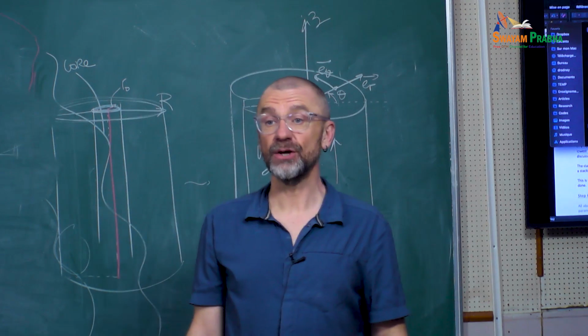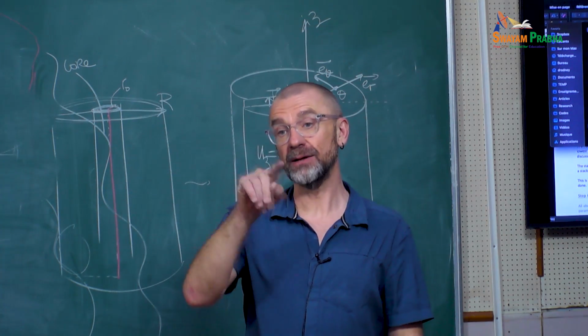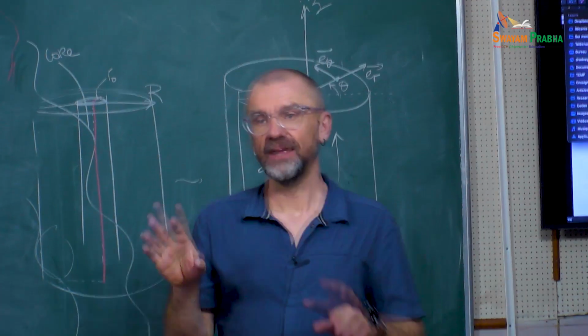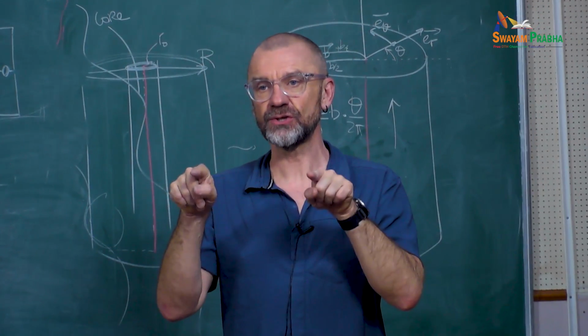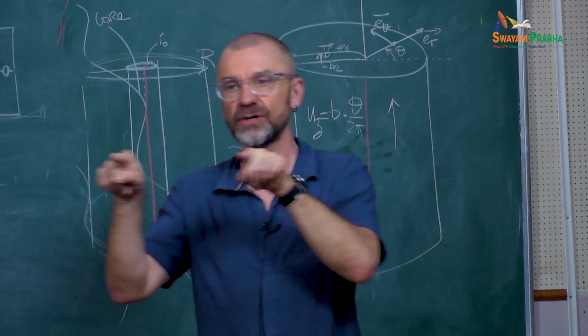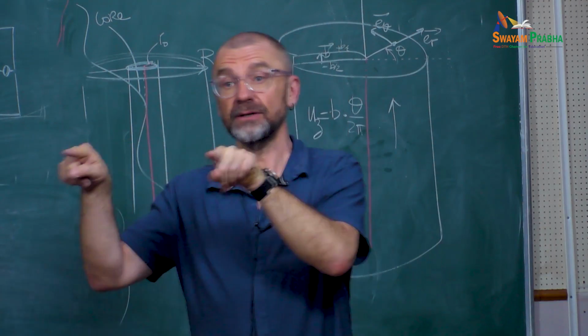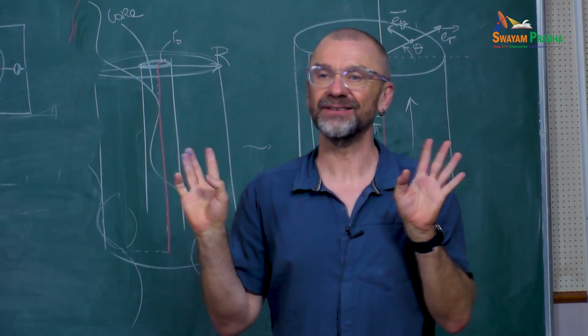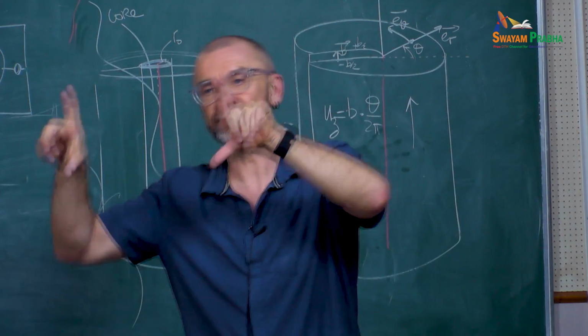If you apply a stress, it does not work. Now, if you compute the Peierls barrier, then the Peierls barrier is computed with no applied stress. What you can do is just look at the energy when both dislocations are moving together. Then they stay at the same distance, and then you're fine. There's no artifact, but you have to move all of the dislocations together.